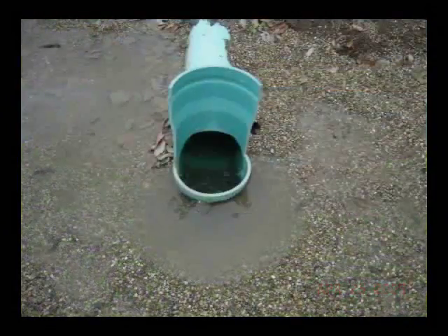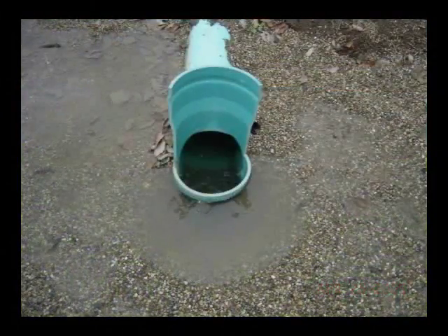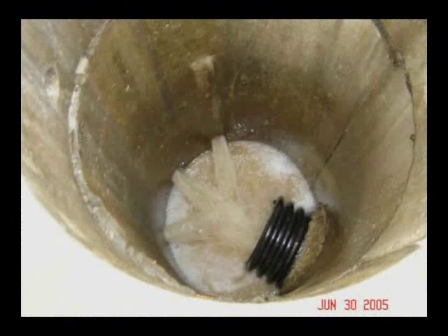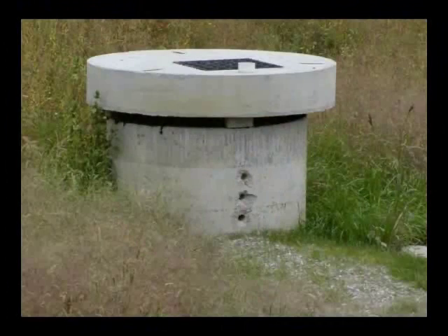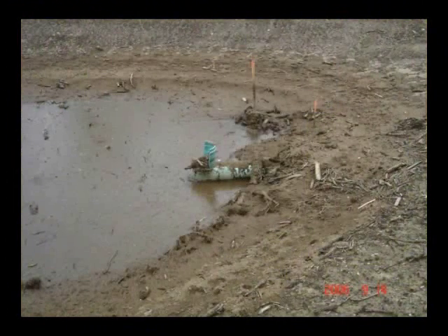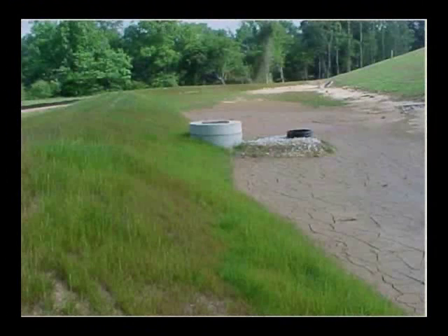It is preferable to drain the basin from the water surface through a riser pipe rather than through a discharge pipe located at the bottom of the basin. This can easily be accomplished by using a perforated riser pipe instead of a pipe with solid walls. To minimize the loss of sediment passing through the holes, the riser pipe should be wrapped with wire mesh and surrounded with pea stone.